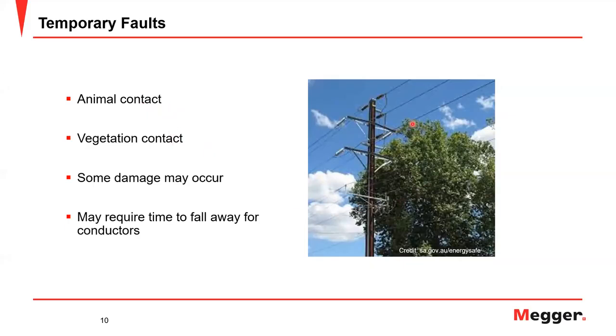In a storm, maybe you have trees blowing and slapping up against a power line. Trees maybe need to be trimmed. Sometimes these need a little bit of time to blow back and recover. And then other times the storm is whipping and gusting and the limb continues to blow over and blow over and blow over, and it accumulates to what appears to be a permanent fault. Many times these things just need a little extra time to clear. So a second and maybe a third reclose attempt will give it time to do that.